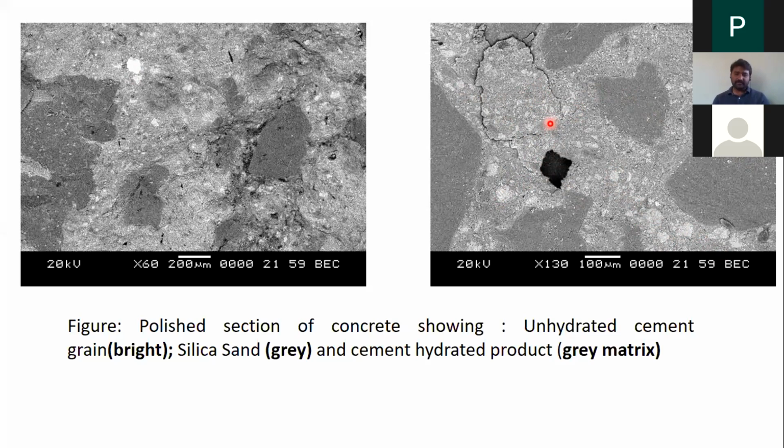image analysis tools. If you feed this image into ImageJ software and threshold with different threshold values, every material, for example voids from 0 to 32 or 34, if you threshold at that value, it will show only voids. Then every other material will have higher threshold values. If you threshold, you can easily get what kind of material is present in that image. Okay, so if you have worked with an image analysis tool, you'll easily catch what I'm trying to say.